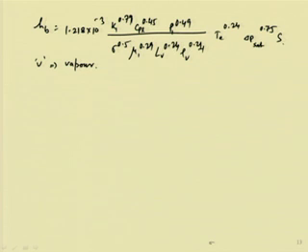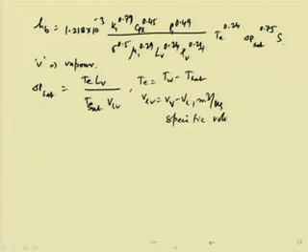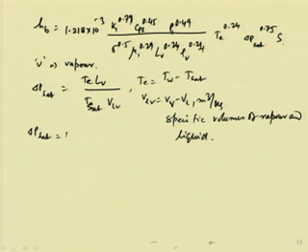okay, this to the power 0.75 into S. Now, here the ΔP_sat is given as (h_LV ΔT_e by T_sat v_LV), where ΔT we know is T_w, wall temperature, minus saturation temperature, and v_LV is v_V minus v_L, this is in meter cube per kg, that means these are specific volumes of vapor and liquid, okay, and ΔP_sat is in Newton per meter square.